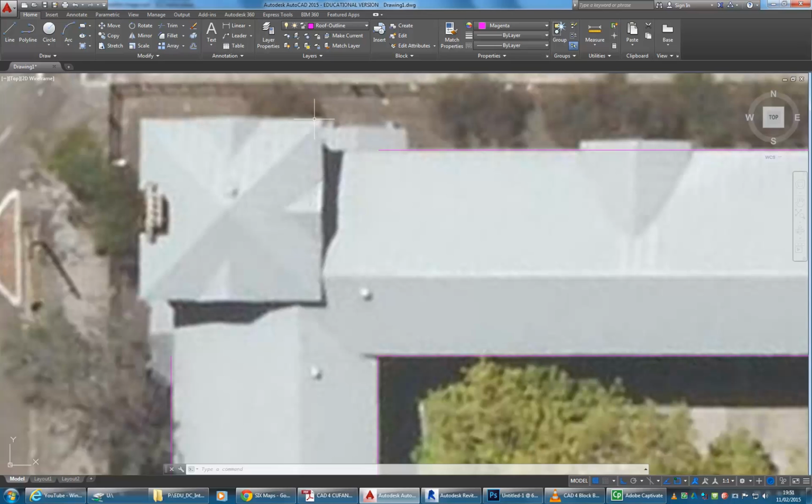So, yeah, and like I said, you'll get a survey as well as a starting point, and they'll give you that in DWG format. And Magic Plan and others export DWGs for you as well. But again, it's not a difficult skill to just be able to sketch out the measurements you need and draw it up yourself in AutoCAD. And then you know it's right, because those programs make your life easier, but they'll also put in a lot of extra things that you don't want. And anyhow, what you're doing here, you'll see, it doesn't take very long.